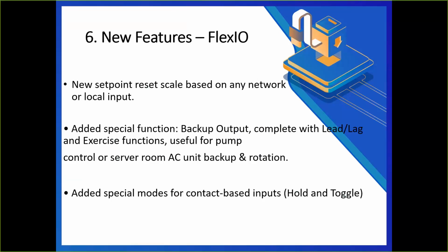We added a backup output. So we now have a second controller that can do lead lag rotation, exercise functions, failover. Our mindset when we created this, of course, was pumps, but you could use this with anything. Basically, it's going to be an output that's going to be joined to an input to prove that output, and then we'll put 2 of those sets together to work in a pair for handling one single function.